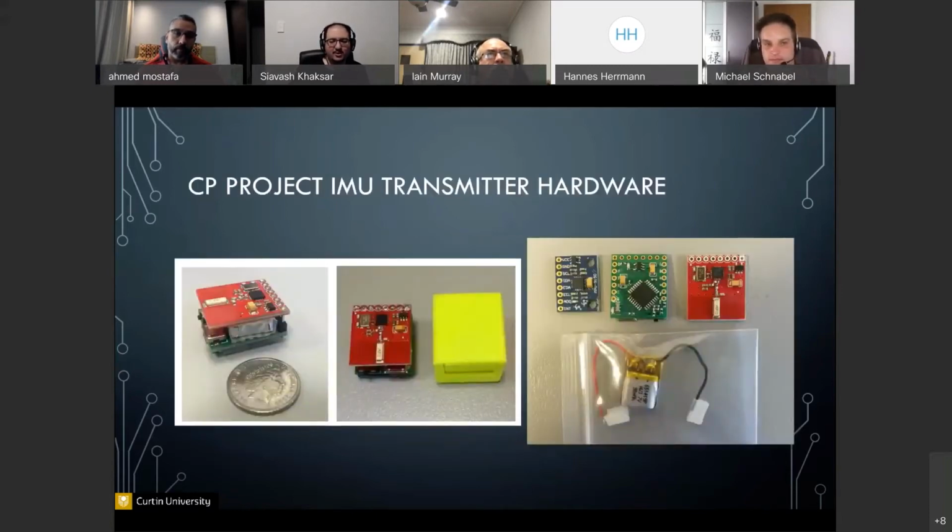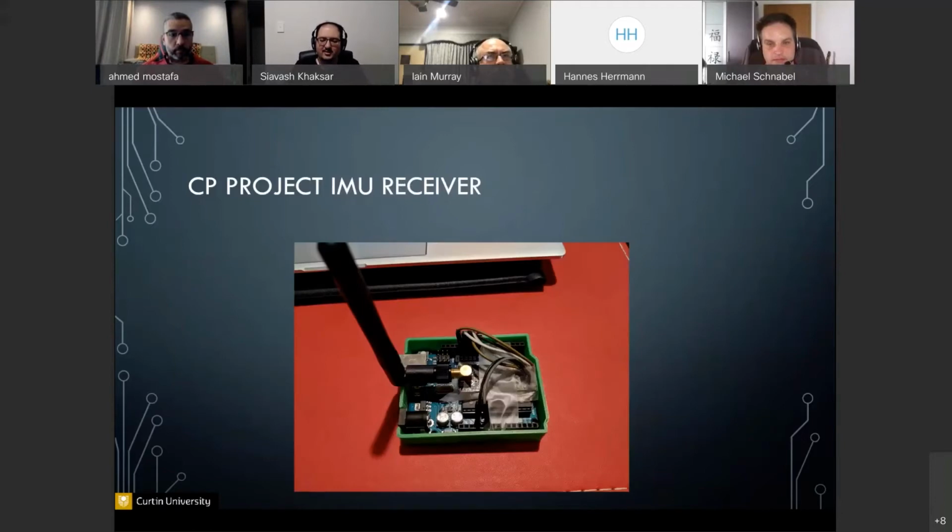Another one that I'm working on uses the same idea: an IMU sensor, a microcontroller, and this one has an RF transceiver. This is one of our early prototypes. I'm using these sensors specifically for looking at joint movement on the wrist, and this is specifically for children with cerebral palsy. I have two of these sensors, one connected to the back of the hand, one slightly above the wrist. Using the data from these two sensors, we capture that joint movement. Again, I like this picture because I've termed it my sticky taped prototype, as it's literally a sticky taped Arduino board to a transceiver.